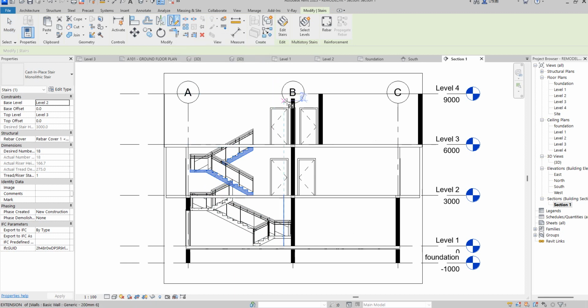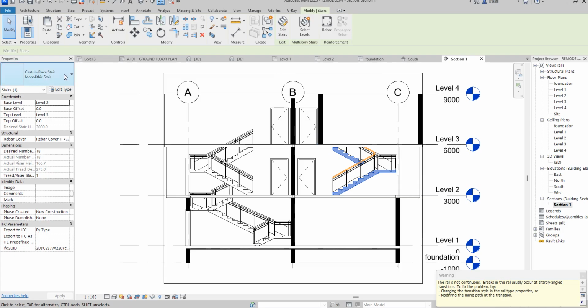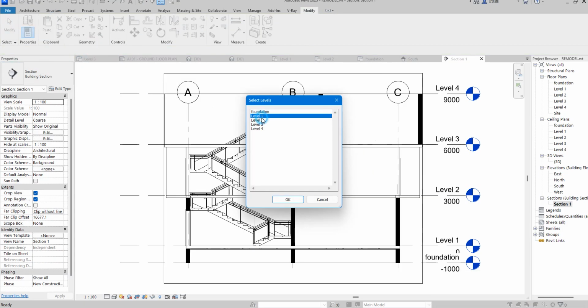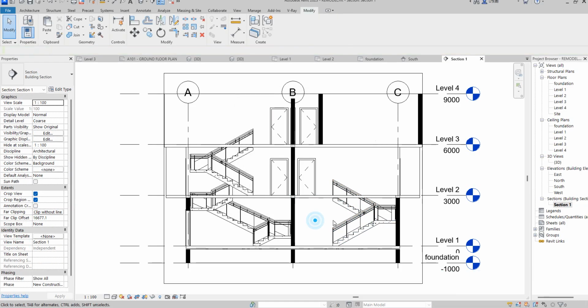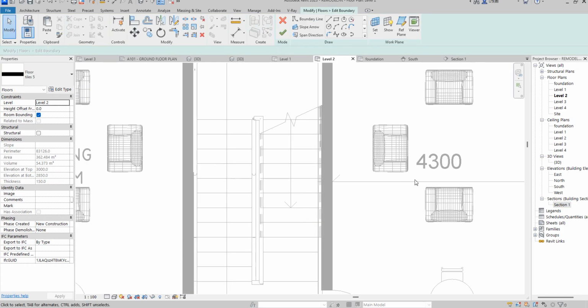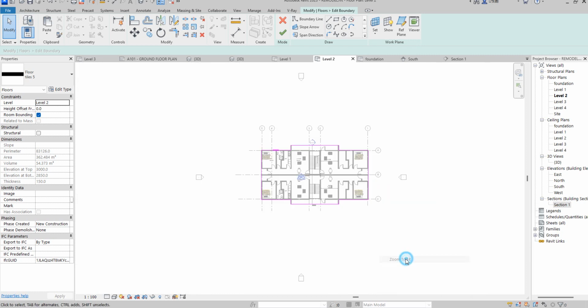So I'm going to say mirror this one. I just want to use that abracadabra. I don't want to start the design, mirror this. Then from here you just say cut, then you paste it on level 1. Can you see? So you place it on level 1. So this is done. So you click here and you remove what you need to remove from the existing part. So zoom out, zoom out.